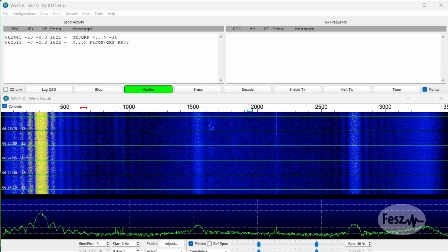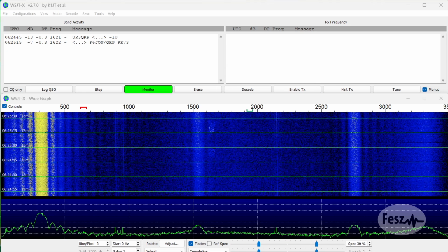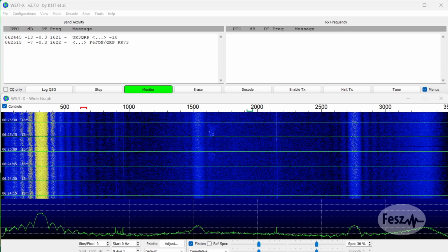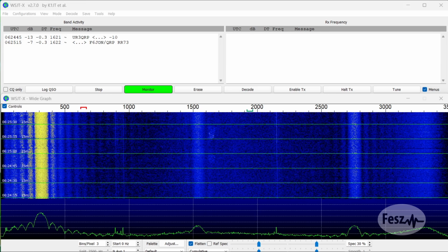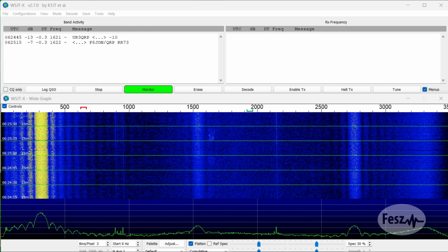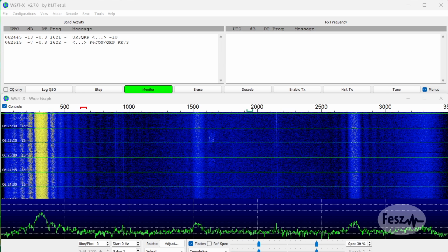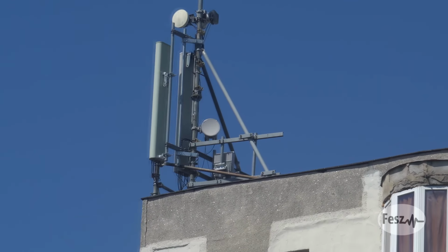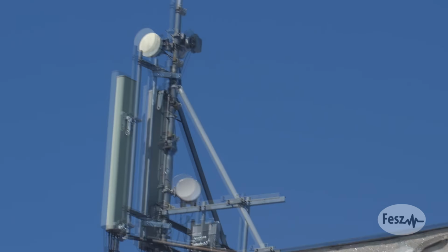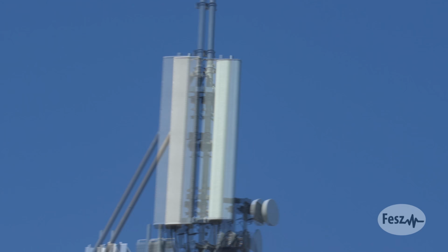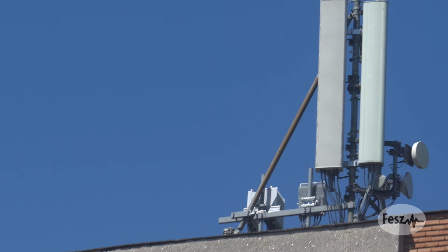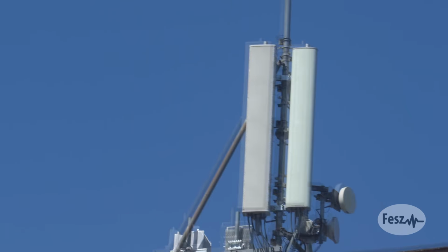Now, in all fairness, the issue I was having did not look either like AM or FM broadcast. It's a continuous, non-varying signal, so I thought maybe it's coming from some other broadcast or equipment. Maybe the antennas and transmission equipment that is all over the city, similar to one on top of my building, maybe that might be generating some noise in the HF bands, maybe from its internal power supplies or something. So that was my initial assessment.